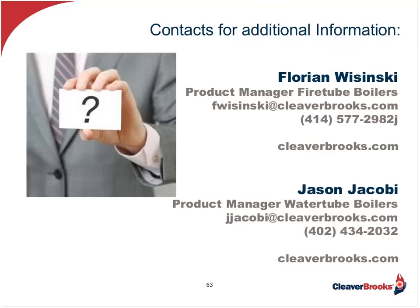Sure. Both the fire tube products and the industrial water tube products have options to be mounted outdoors without a boiler room. A number of our customers do that. We have sites like that. The things to consider are, number one, we need to make sure that the controls are put in a weather-resistant, water-resistant type of enclosure, so the controls need to be properly set up for outdoor installation. The other thing that comes up is that the variation in ambient temperature can have an effect on boiler efficiency. So there are control systems called O2 trim that can compensate for some variation in outdoor temperature.